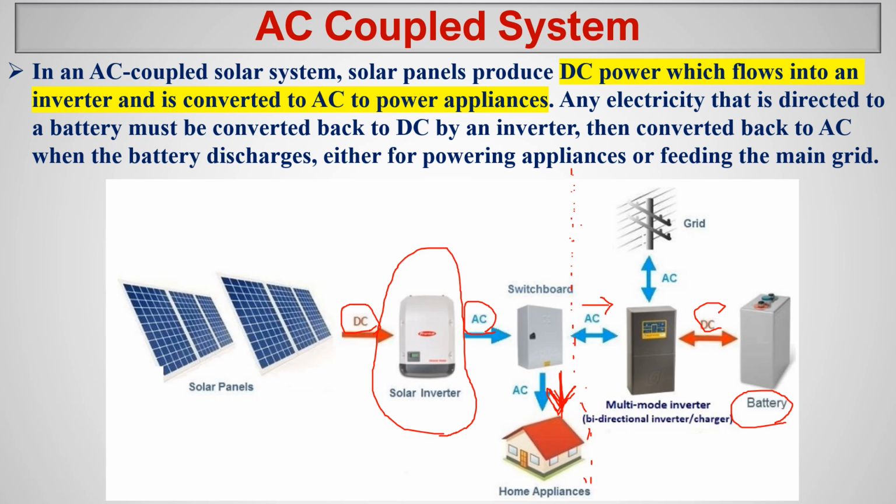Then why do we need a hybrid inverter, a multi-mode inverter here? Because look at here, grid. We can charge the battery by grid as well. Because this inverter, I'm going to use a smart inverter, a hybrid inverter that can use the power from solar PV to charge the battery, and also power from grid to charge the battery. And that is one of the reasons.